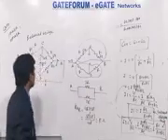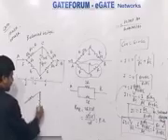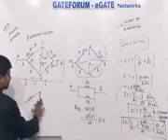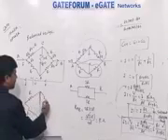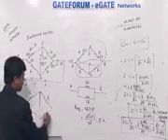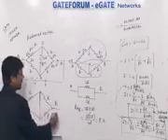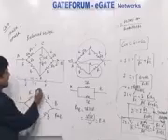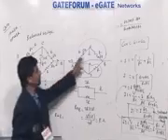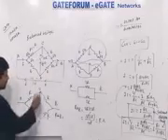In a similar way, if 2 resistors are connected like this, I don't have any resistor here, but these resistors are same, R, R, R and R. The resistance between point A and B, RAB, is equal to, now I can say that C and D point here we consider as an open circuit because current is equal to 0. Still it is a balanced bridge. These points are shorted.